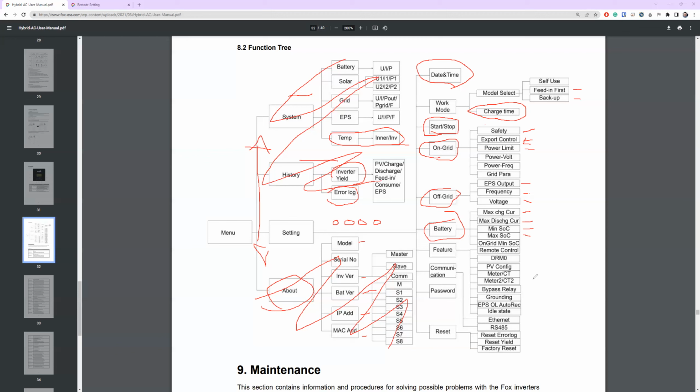The only time I've used this is when I deliberately wanted it to stop charging past a certain point on a forced charge overnight. So I know it's going to be okay weather tomorrow, but it's not so good that I can get away with not having any forced charging. So what I can do is set this to say 60% maximum state of charge. It will charge it up to 60% during the forced charging window, and then stop at 60%, and then wait for that charge window to go past before starting to provide power to the house.